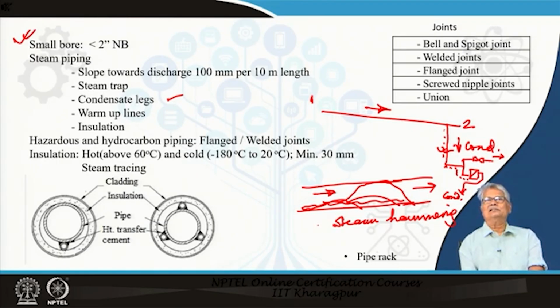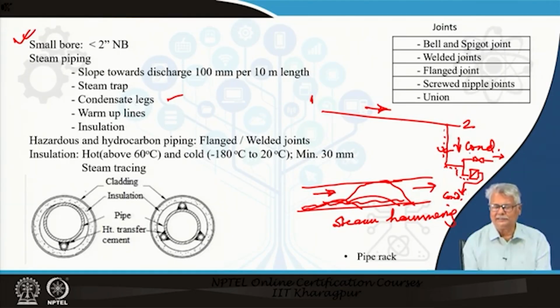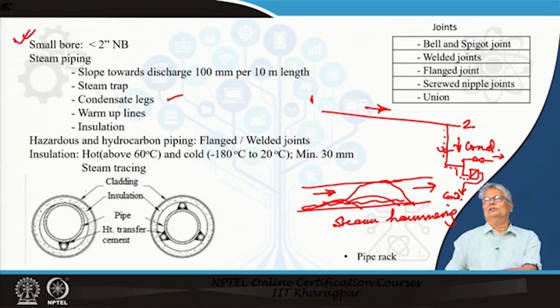Now, whenever you charge a steam pipe, initially the pipe is cold. So, quite naturally what would happen is the amount of steam which enters the cold pipe would condense. So, you will be having a huge amount of condensation initially. So, the steam trap is not enough. What you have in that particular case is the condensate bypass line, which also takes out this extra amount of condensate, and this also is an essential part in that particular system, and it is open in order to cope up with any additional condensation.